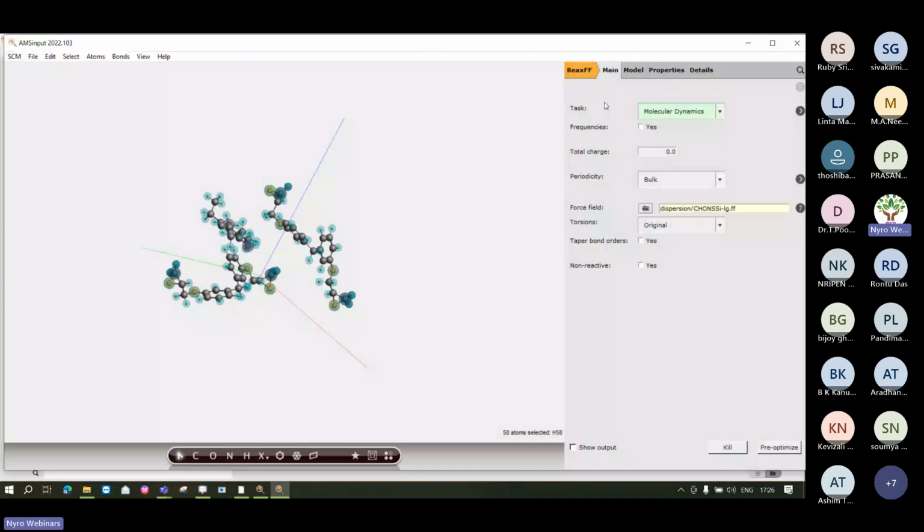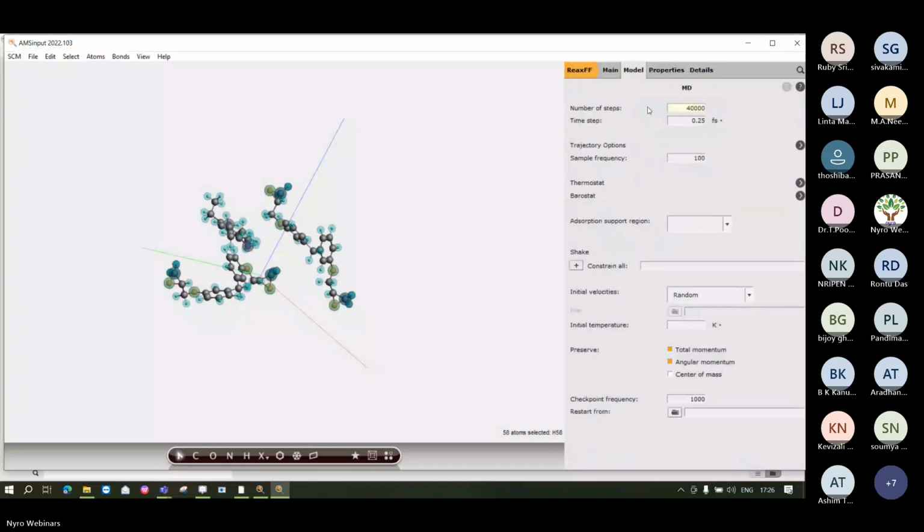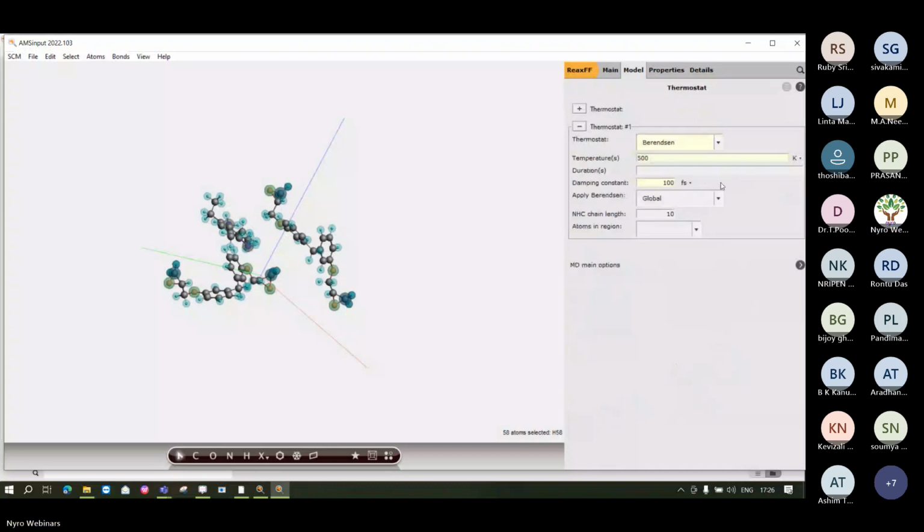So why have I selected this thermostat? Because it is an approximation to the correct ensemble, and the approximation is best for a shorter damping time. In this case, generally the crucial part is to set the damping time as high as practical to still reach the target value in an acceptable time.